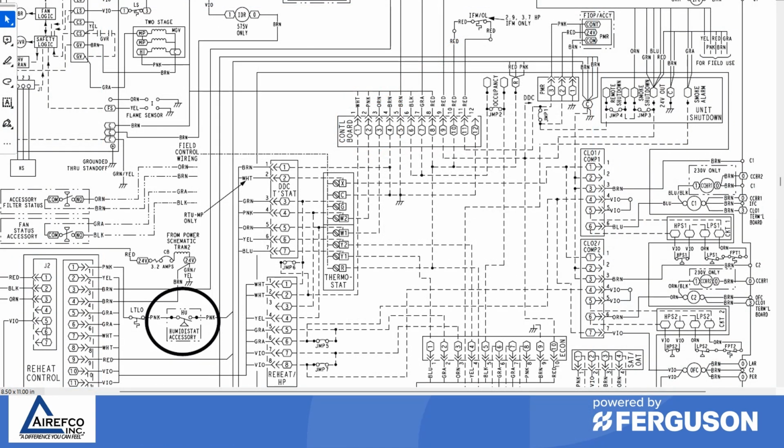This diagram is of a larger system that has two compressor circuits. And again, you have your low and high pressure switches on both circuits. And again, you have your wiring going back to the control board. So even though the switch may show that it's closed, it may not show it closed back to the board through the wiring and the plugs. So on every system, you need to double check the wiring to make sure that the closed switch is communicating back to the board that it is definitely closed.